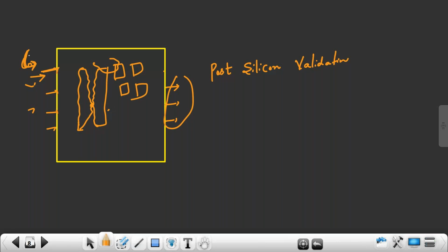So when I apply any test case, I should know where it is going, where the logic 0 I have applied is going, through what gates, and what is coming at the output. I should know what gates are present inside. I should have that control. To make this control possible, my DFT team will add some additional logic, additional cells, inside this.